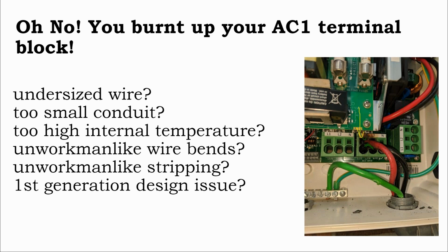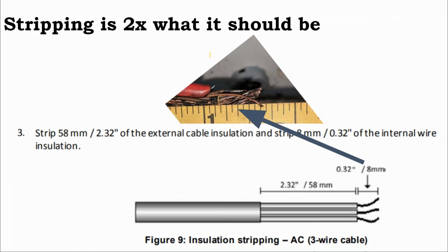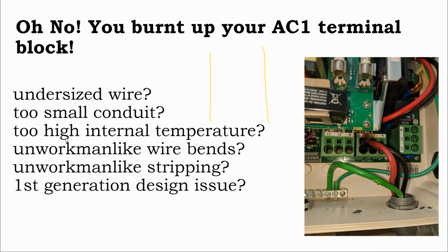And so one thing that I think do-it-yourselfers should take under advisement is that these terminal blocks for these power inputs are right next to each other. There's not that much space between them. So if you get things wrong, like stripping too much wire off of the end of the cable, on an AC breaker panel, things are a little bit further spaced out than in solar equipment, and solar equipment is quite expensive. So this was basically a $3,000 piece of equipment that was bricked, because the manufacturers are not compartmentalizing their control boards and letting you take a control board and put a new one in. They swap out the entire unit.